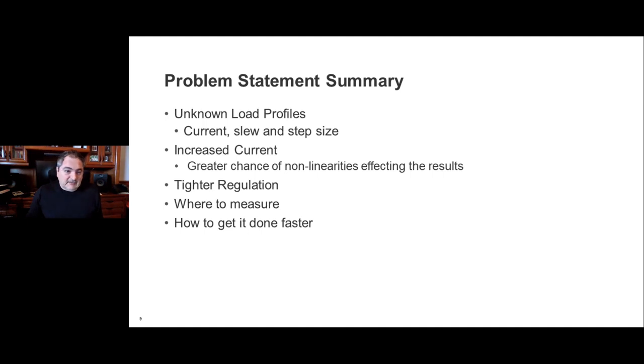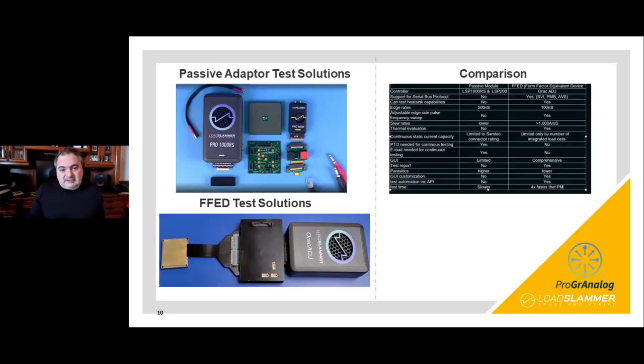and making sure that these devices go to market tested on the system boards. And then last but not least, how to measure, where to measure. When it comes to the Xilinx devices, we're okay because there's a clearly defined place on where to measure. And you'll see in the products I'm going to show you now that we have the same test place locations that have been determined by Xilinx ahead of time. So when it comes to the Xilinx solutions that we offer, all those important measurement points have been defined ahead of time.